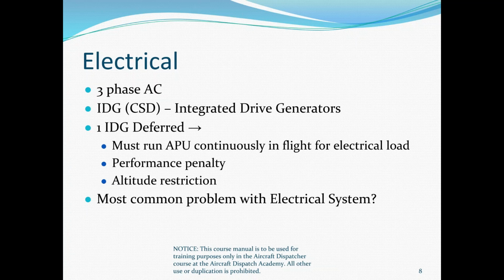I look to my right on my notes and it says, if only one AC is functioning, flight is limited to flight level 31,000. It also happens to say the APU burn is 260 pounds an hour. So I'm awesome. I'm not going to watch this screen, I'm going to look at my other one.